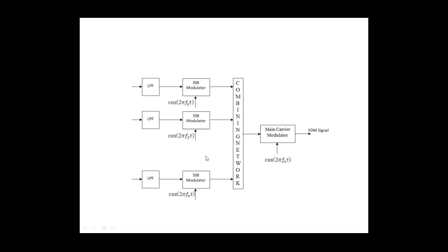Here in this transmitter, at each and every location, you see, this is the input, one input, this is another input, this is the nth input. Like that, there are a number of inputs. Okay. So let us see how these signals are frequency division multiplexed. So this is message signal 1. Okay. And this message signal is allowed to pass through a low pass filter. Okay. Because all message signals must be first band limited. So how can we band limit a signal? Just by passing the signals through low pass filters.